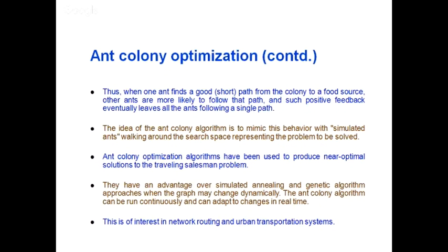Now I worked on a problem that is basically maximization of cutting tool life. I introduced it earlier also, that we had T, tool life, is equal to V, F and D raised to some powers. Now this becomes the objective function. The objective function is to maximize T, which is in the form of an equation: V raised to power A, F raised to power B and D raised to power C.